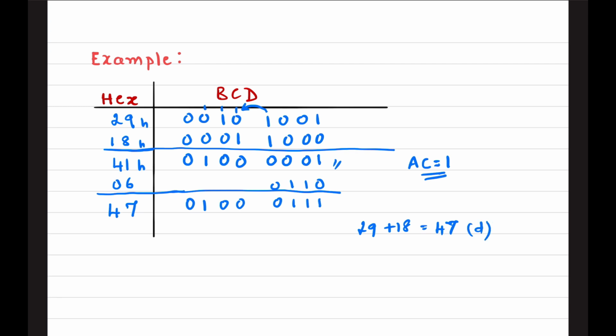But what actually happens inside is a hexadecimal operation. So we need to convert the hexadecimal result we have got to decimal. At that instant we make use of the DAA instruction. Once we get the result out of the add instruction, the result will be stored in the accumulator. After we get this result, we use the instruction DAA.